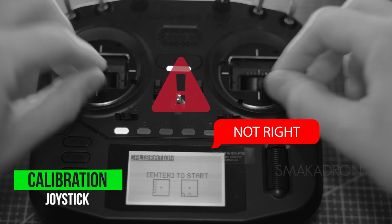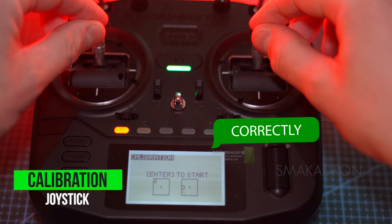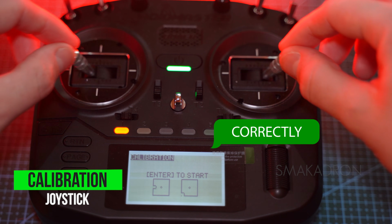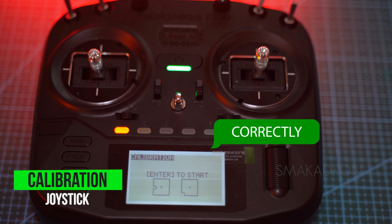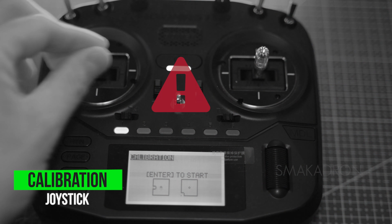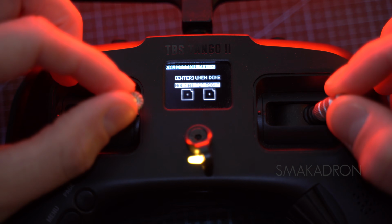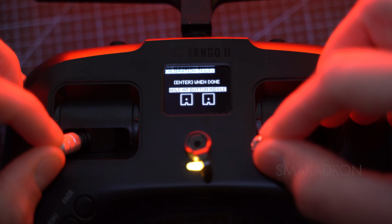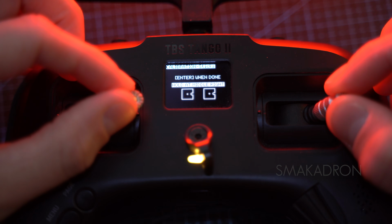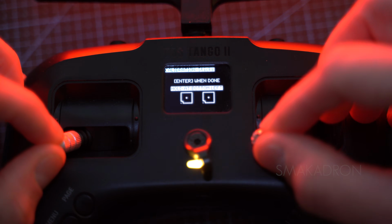Actually, for proper calibration of the radio transmitter, you should not move the sticks in a circle as many people do, but only up, down, and left, right until you feel a slight resistance at the endpoint. There's no need to press hard to the edge of the stick's travel. You wouldn't do that when flying. By the way, for calibrating a radio on the FreedomTX firmware, you actually do need to rotate the sticks in a circle. And so, we begin calibrating the radio on the EdgeTX firmware.